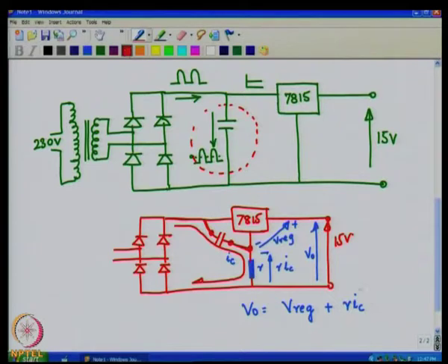Now, this portion is unregulated, is something that we do not want. We do not want it to come to the output, but this is an error that will come on to the output, deregulate the output by virtue of routing which is as such like this, whereby the capacitor current flows through this parasitic component small r here, lowercase r, which is trying to couple some of the unregulated portion to the output. This is one of the issues that can occur when you are doing the PCB layout and routing, and one must be careful about this.